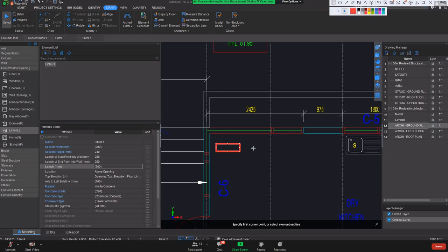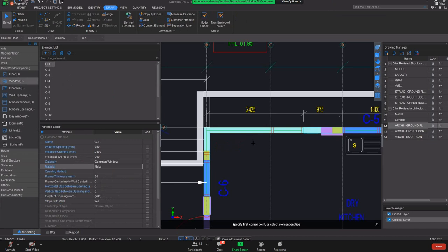I would suggest you make sure with the architect what the window code is, and if the window code is not in the window schedule, please revise the window schedule. Meanwhile, you can add the window in the window list, and then you can just point it. So if the information is there, it will automatically generate. Yes, you're right. Correct. So if there is no information, it won't generate out.